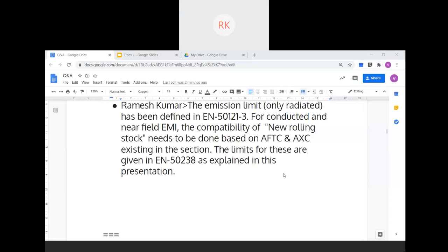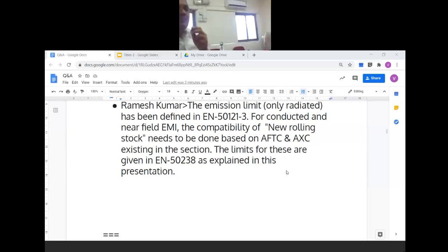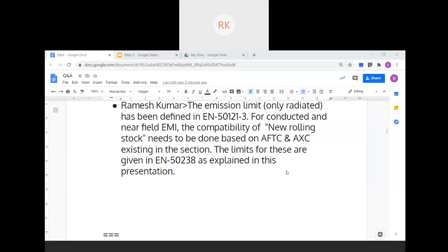And third, there is a requirement that the BTM and the BTM antenna has to be in the shortest distance possible. Many times we found that we had to position the BTM in between the two bogies. The length of the cable was crossing the recommended distance. It was leading to pickup of interferences. Much of the ETCS level 1 problems initially on southern as well as northern was basically because of EMI EMC references. A lot of things can be done.